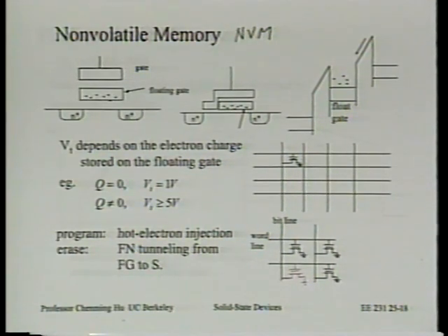If not, then we'll give it perhaps 2 more pulses before making that measurement, called verification, again. If it's verified, then that's in. If it's not verified, we'll give a few more pulses. And typically there's a limit of how many pulses you're willing to apply before the circuit just gives up, saying it has died. This memory is no good. So there's a reliability issue you can see.